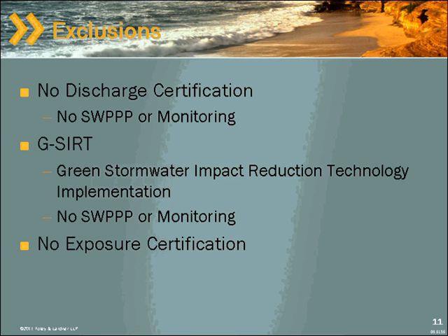No discharge certification is really pretty clear. Get your licensed professional civil engineer to certify that you can contain a 100-year storm event on your property. After you contain it, you can infiltrate it, you can evaporate it, you can use it for process water, you can send it down to sanitary sewer, you just can't discharge it. And that may work for some people who have needs for those waters, uses for those waters, the right kind of soils or locations where it can infiltrate, where you can demonstrate that there cannot be, and there is the other qualification, or you can demonstrate that there is no possible discharge to a water of the United States. Certainly something that people should be considering as an option.